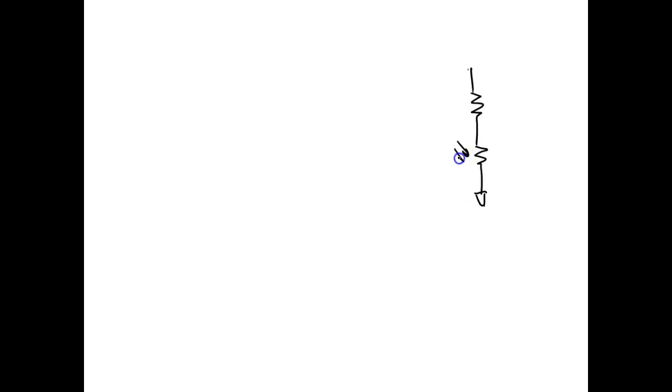So this will be my photo cell down here, and then my light bulb would be right here, and then my triac would be right here. And then this would be my neutral. And then I'm going to gate it. Now this might work, but it won't work real good.